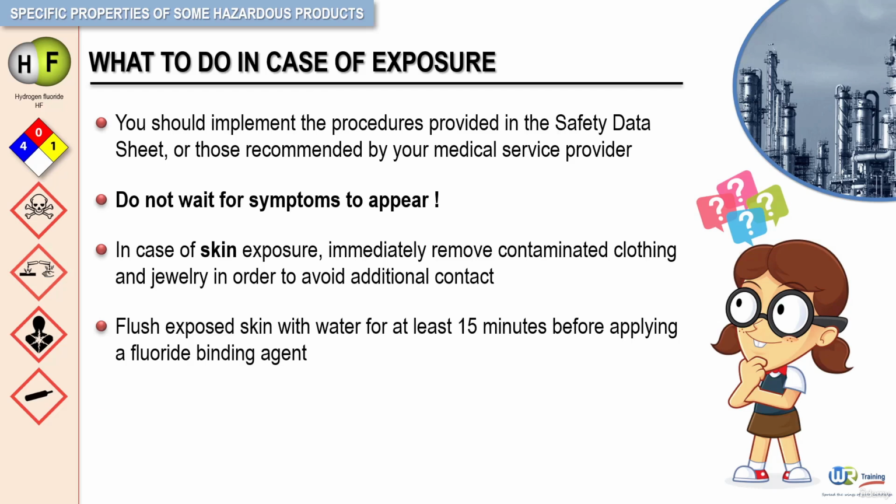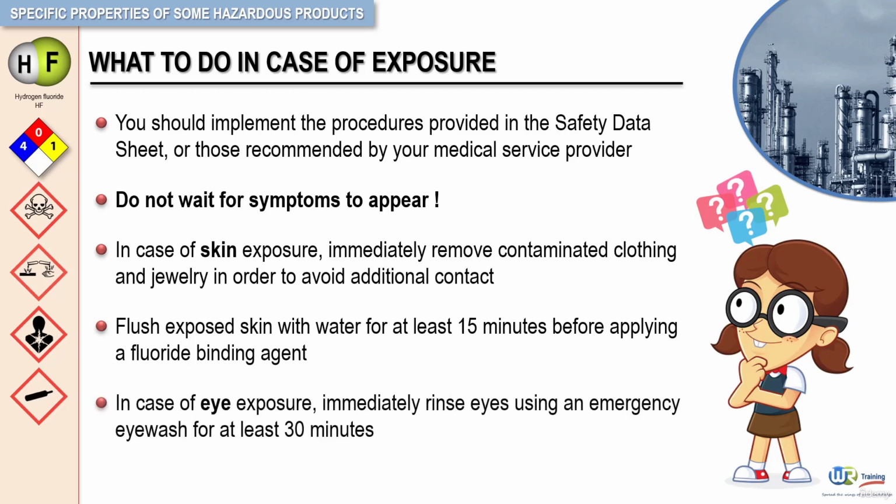In case of eye exposure, immediately rinse eyes using an emergency eye wash for at least 30 minutes. Don't forget to remove and discard any contact lenses. Lift eyelids and move eyes to ensure complete irrigation. After that, the exposed worker should be urgently transported to medical care.